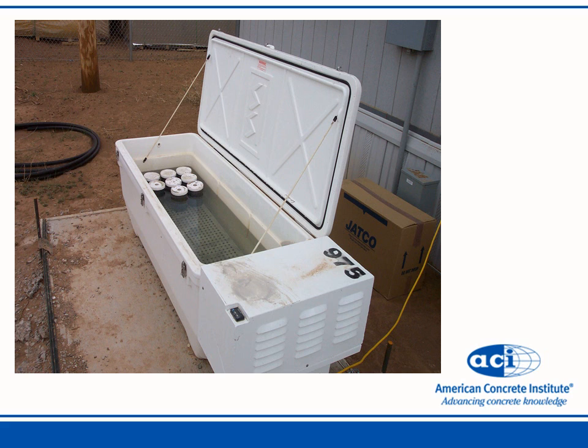Now, this is a Thermo 2 curing box that we had purchased and taken to a job site. These 8 cylinders show them in the curing box. However, water is to be added so they're completely submerged. These are in the water, and the temperature is set at about 73 degrees, and they'll go up or down about 2 degrees. Keep them at that temperature. If you fill it with cylinders, it runs on the cool side to keep the water cool, so the cylinders do not get over 80 degrees.